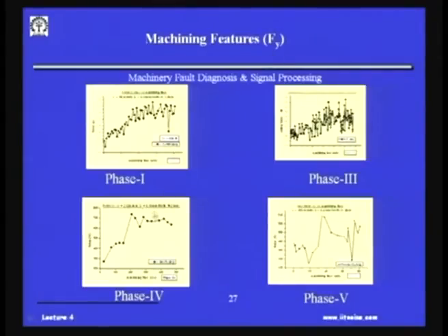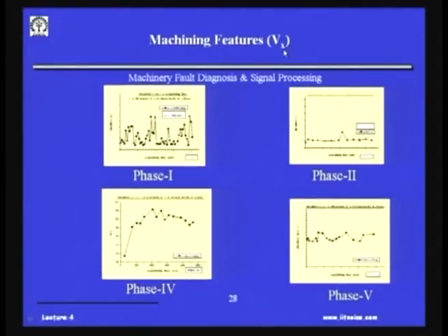Similarly for Fy, prediction in the laboratory and then prediction in industry. Similarly for the vibration in the x direction, we again have machining time, because once we know that the levels are higher or not allowable, then we can also predict the remaining machining time by which this cutting tool has to be replaced.